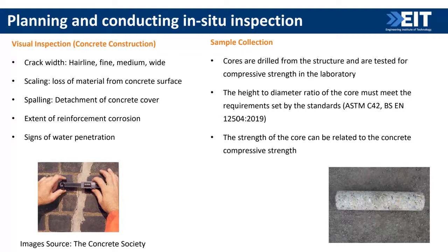And at the same time, in situ, as I said before, we can compare the concrete characteristics in situ against what we had from the previous experiments working with concrete samples. You have these cores, as you can see, drilled from the structure, and then we can conduct simple compressive tests. The main purpose is that it can be more realistic, right?